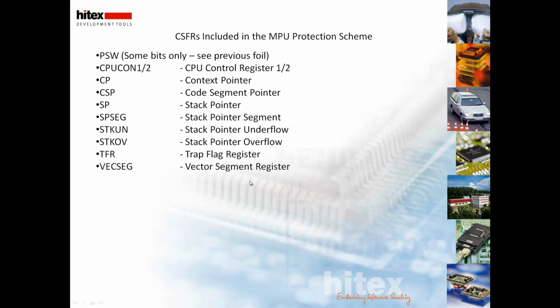Similarly, within the SFR register space, some are included within the protection scheme. So the CPU control registers, for example, the context pointers and the stack pointers. These are protected registers which you wouldn't necessarily want activity within level 1, level 2 or level 3 to alter. So those are protected, and these will generate a trap event if you attempt to change some of these.